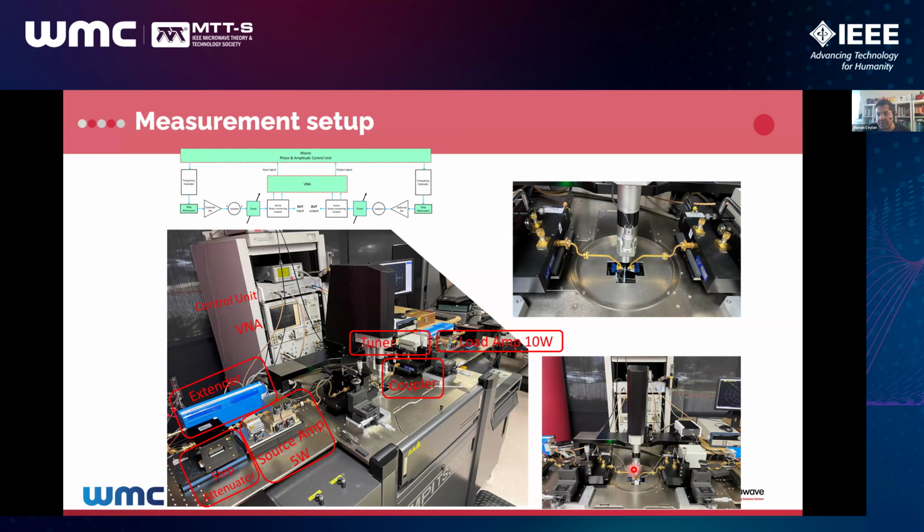So this is a millimeter wave setup, and one of the key components here, we have active down converting couplers, and this is a special design, especially for this type of setup. That's why we have a calibration at the DUT reference plane, vector calibration, and all measurements are vector. So you have amplitude and phase information at the input and at the output. So at the end of your measurements, you will get a lot of information about your device.